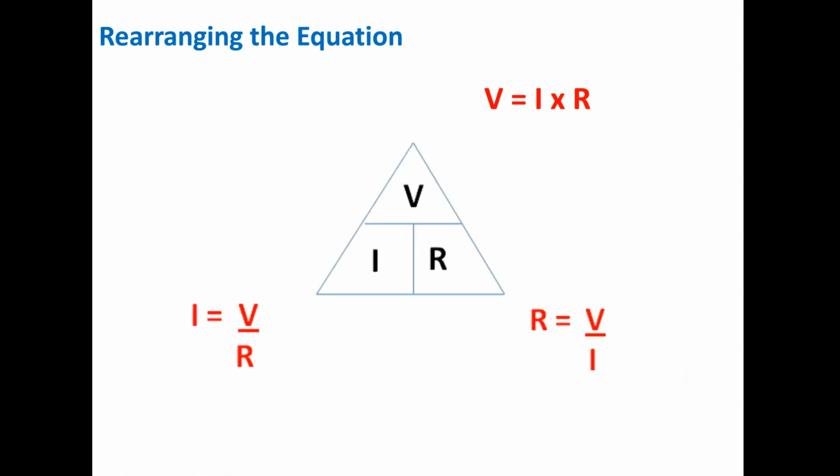So you can also rearrange those equations to figure out what is required if you're looking at different problems. What I usually do is called the thumb rule. Whatever you're trying to figure out, whether it's resistance, use this triangle. You just memorize this triangle. If you memorize one, you can figure out how to get the others by process of elimination. What I've told other students is that you just cover the variable that you're trying to figure out with your thumb. If you want to figure out the resistance, you put your thumb on the R and you figure out that resistance is equal to V over I. If you want to figure out voltage, you put your thumb on the V, and voltage is going to be equal to I times R. Okay? You can figure that out very easily. I'm sure you guys are smart.